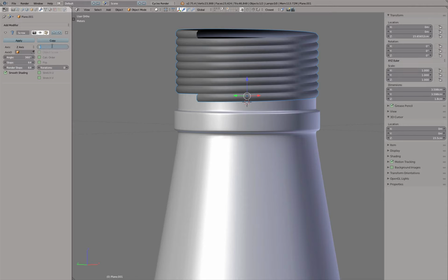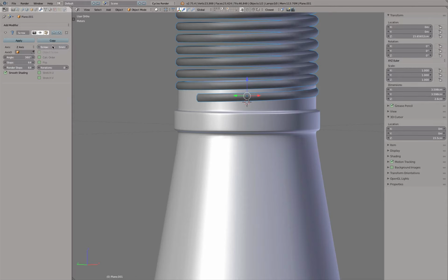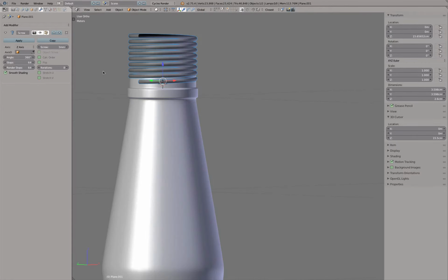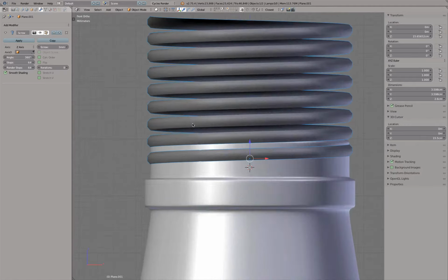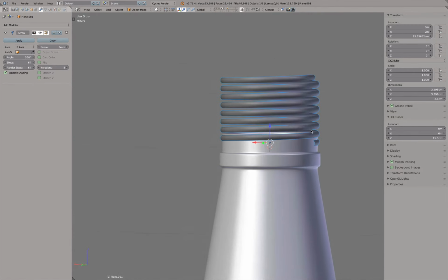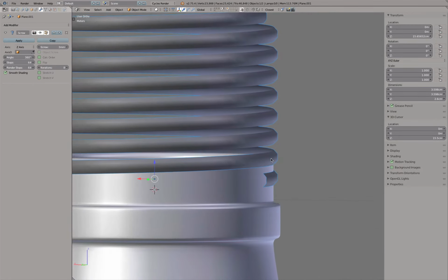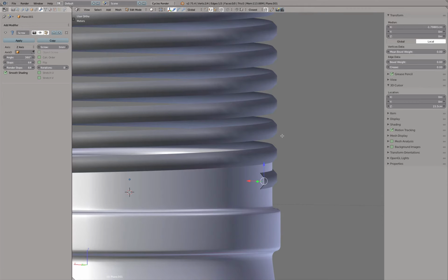If now, for example, we say 3 millimeters, we have 1 millimeter of a gap in between. So very simple actually to create custom threadings this way. Now, because this all is based on this polygon model, or in engineering terms, sketch, when we scale this one, you see how the complete threading adjusts. So this is pretty awesome.